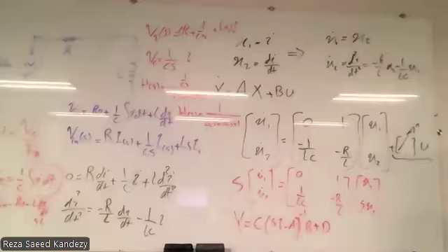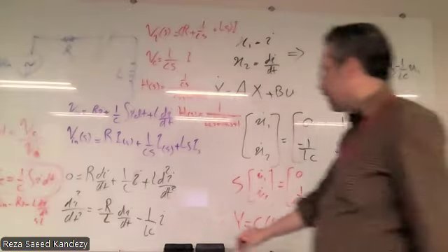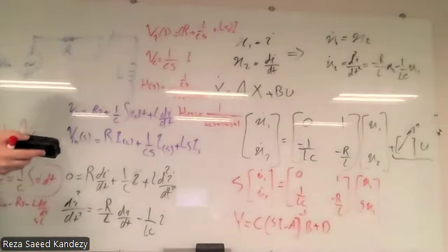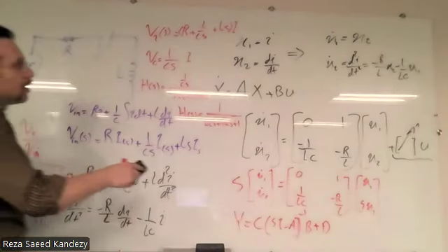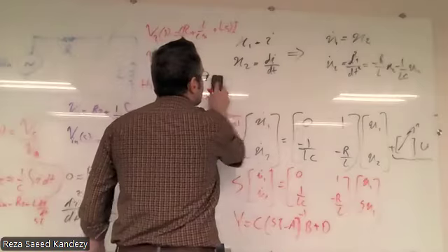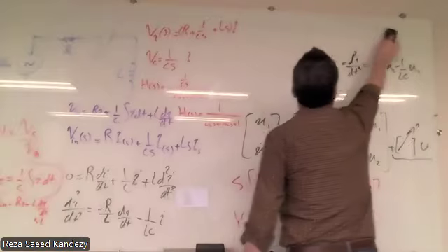How can we find the impulse response, impulse, not the step function response, of a transfer function? Impulse is delta. So just take the Laplace. Okay, let's do that. I have to erase this state space.